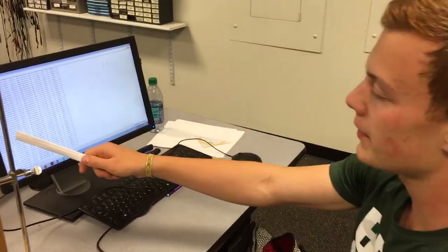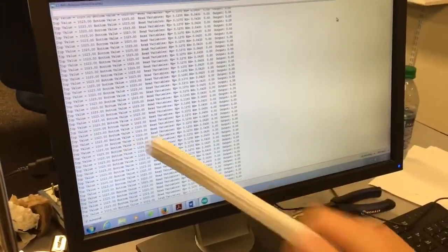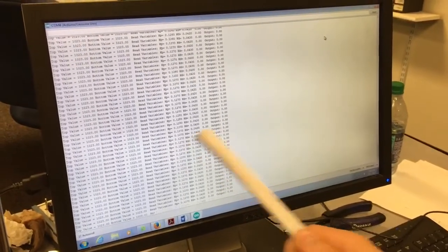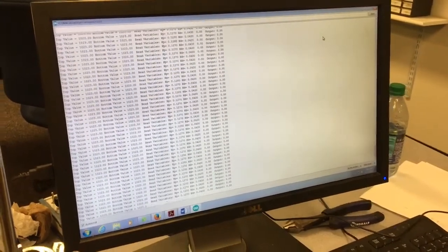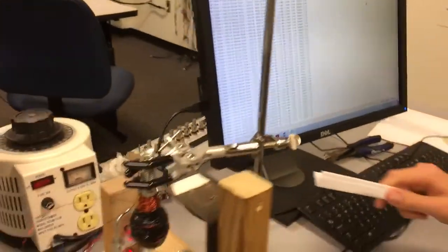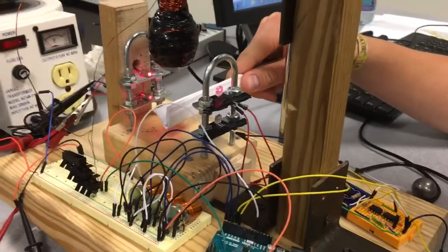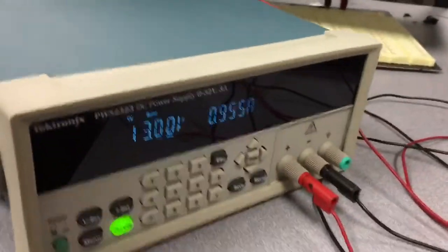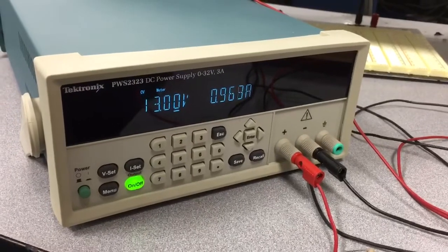This is our serial monitor. Here we can read the top value of the sensor, the bottom value of the sensor, read the variables KP and KD, and monitor the output. Now we want to test what happens if we block the bottom laser first. Of course, it makes sense that the output rises and we get a higher current than before.